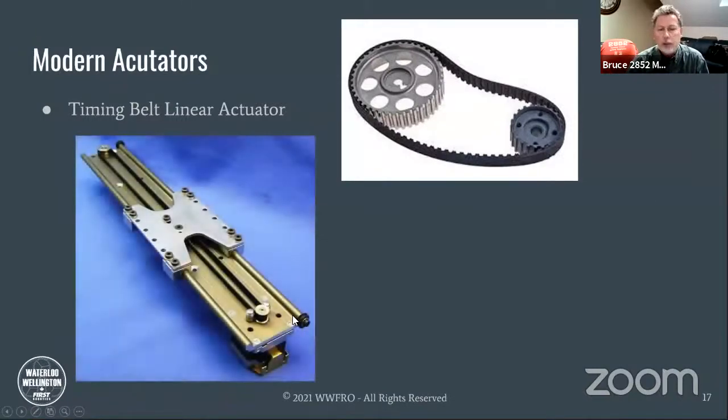And this is how they might be used for a rotary to linear application. You can see the poly belt here, a sprocket at top and bottom of this device, and then a table. The belt is connected underneath here at this point. And as we rotate the belt, this table will slide on these guide bars down and back up.